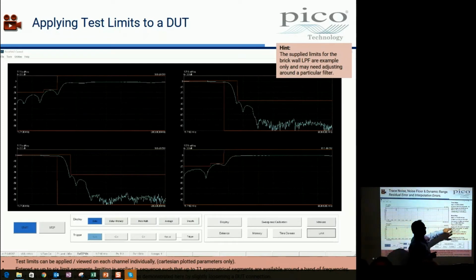So we're going to be looking at minus 115 dBm RMS for our noise floor. That's what the spec says it should be. And that is 400 nanovolts RMS. That's pretty small, especially as we're looking at 4 gigahertz signals. We're expecting 3 times RMS noise peaks, so the peaks are going to be falling at around 1.2 microvolts, which translates to minus 105. As you'll see in this demo, we don't quite make it, but then we'll show you how to make it. But let's do this one first.